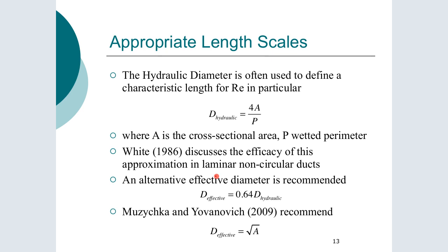arbitrary shaped channels. So previously what we covered was the Fourier derivation of the fully developed rectangular velocity profile. And that was quite a hairy looking equation that we had. And what we're moving on to now is a general equation that we can use to calculate the pressure drop for a given flow rate in an arbitrarily shaped channel.